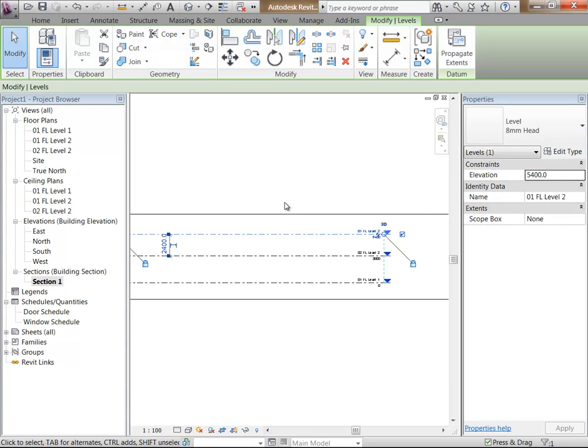There are tools in Revit for managing survey points and establishing either a relative or an absolute way of measuring your heights. But what I found is that if you just use this as AHD, so you set your ground floor to whatever AHD height you've got in millimeters, and then just do the other levels from there. Works really well.